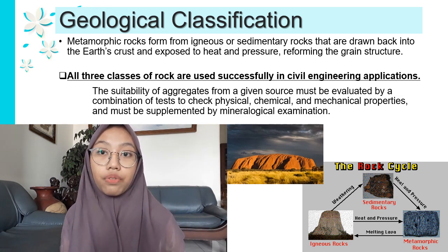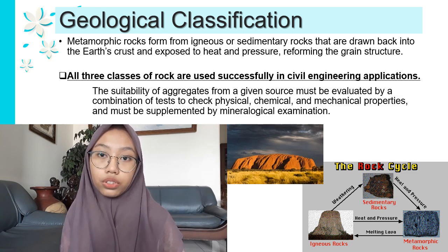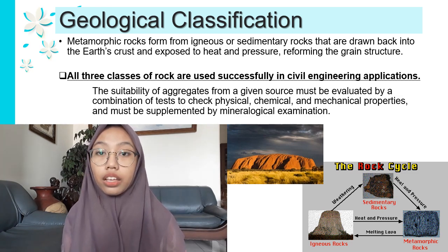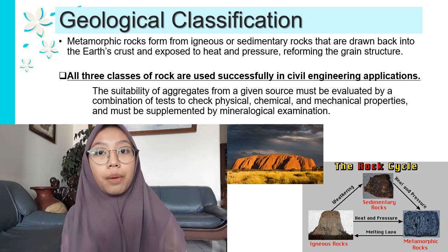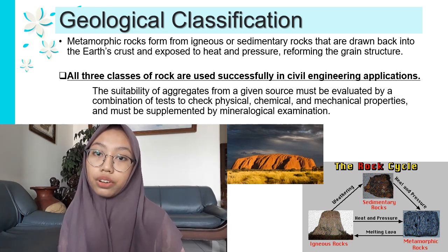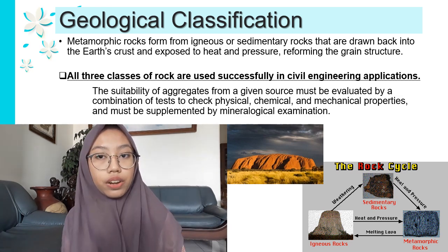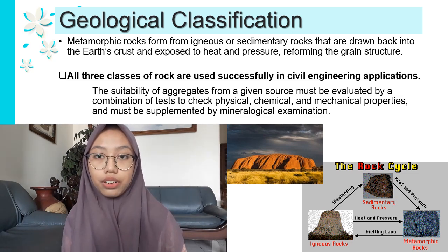The suitability of aggregates from a given source must be evaluated by a combination of tests to check physical, chemical, and mechanical properties, and must be supplemented by mineralogical examination. The best possible prediction of aggregate suitability for a given application is that based on historical performance in similar design.